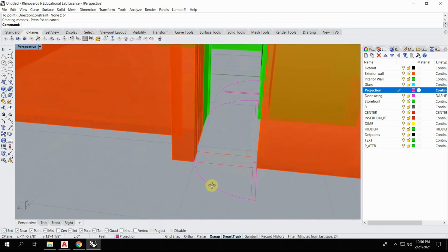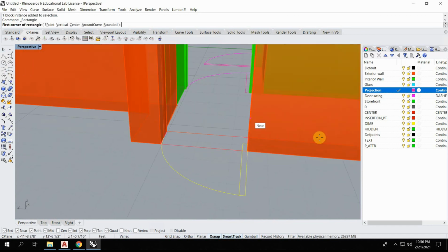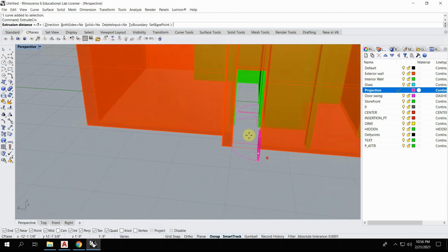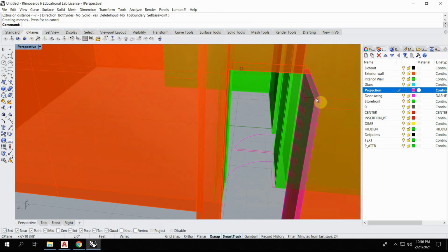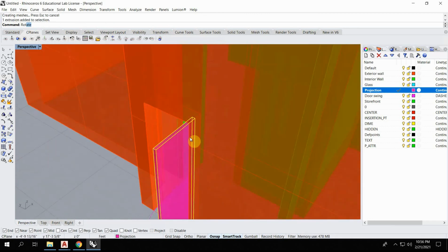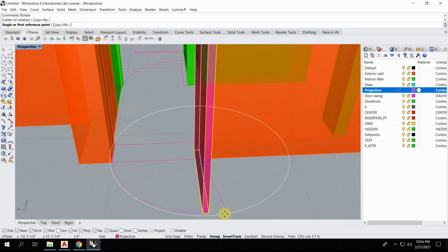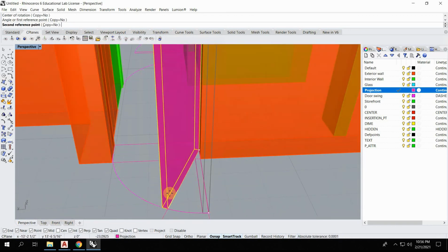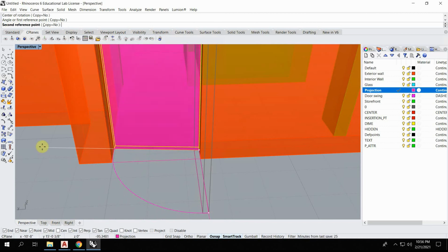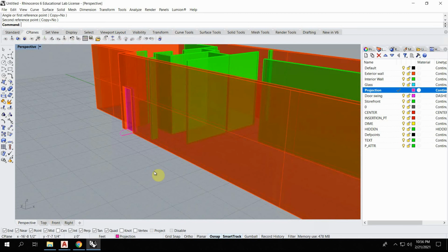We don't usually model the door out, usually model the door in, but I could still use this rectangle here, extrude that. And I can just reference the other one here. And then I could even rotate that in. So if I type in rotate, I'm going to give the center of rotation as the pivot point of that door, and then you can see it actually follows the door swing, and we could shut the door here. Okay, so that is an example of that.